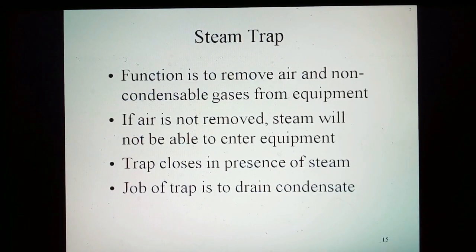The first function of any steam trap is to remove air and non-condensable gases from the equipment to which it is assigned. If the air is not removed, steam will not be able to enter the equipment. Hence, heat transfer will not occur. If air is not removed as designed, you may get uneven heating among different components, poor steam distribution, and possible corrosion. The next job of the trap is to close in the presence of steam. The last job of the trap is to drain condensate.